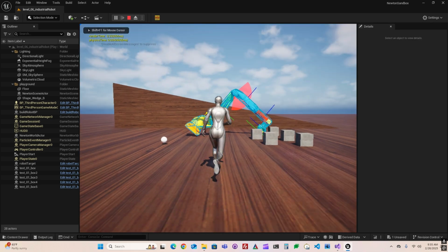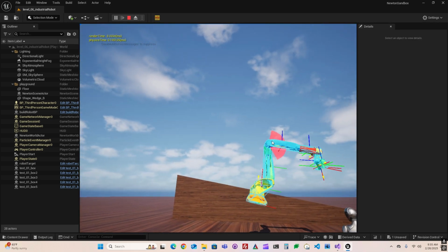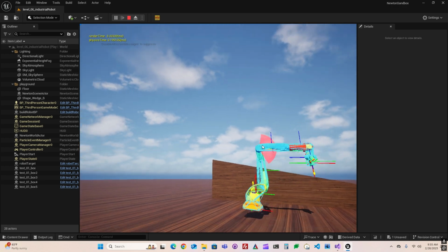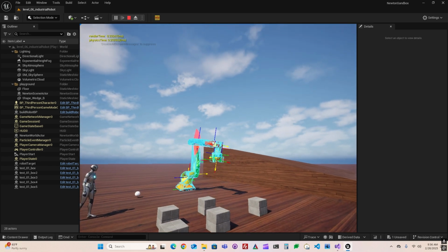If the robot still behaves incorrectly, recheck gripper motorization. Fine-tune joint limits and mass values. Adjust the effector force. Repeat this process until the robot moves as expected.